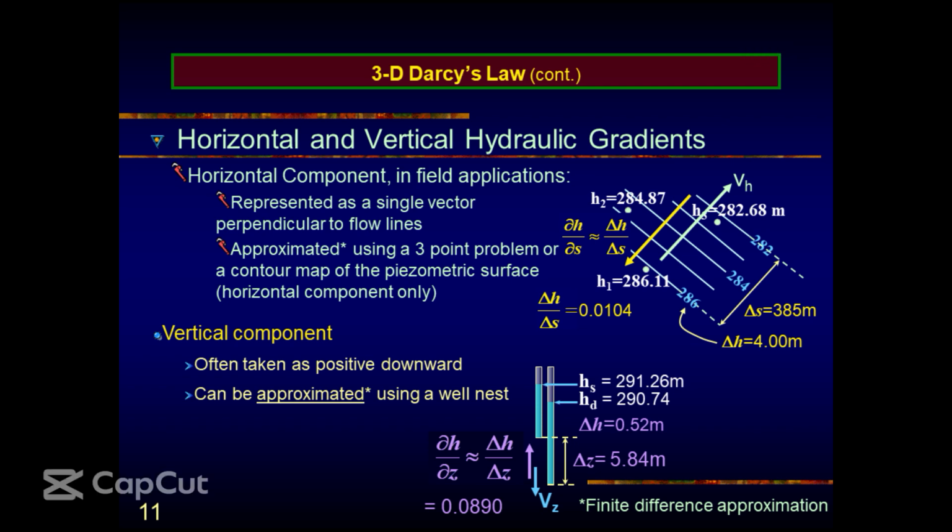And the piezometric heads, how do you determine it? The elevation of the surface minus the depth to the surface of the water, isn't it? This is like in practice. You have your GPS here, you take the surface elevation. Let's say it's 500. What's the elevation of Abu or Zaria above mean sea level?